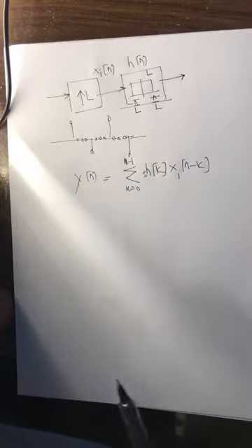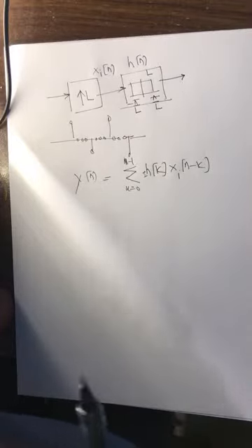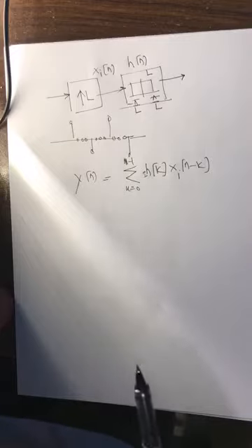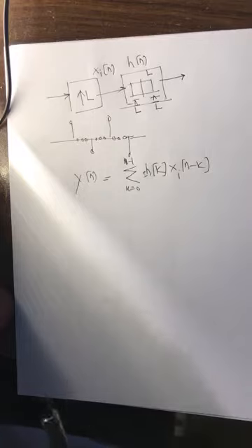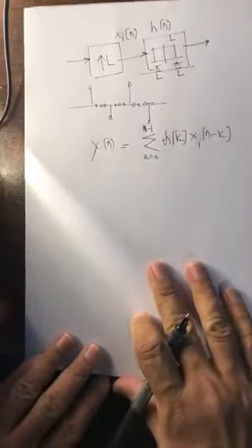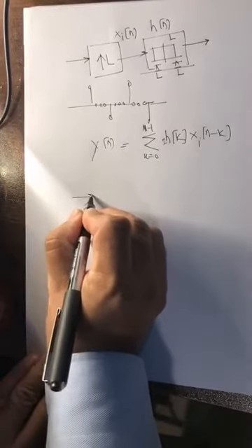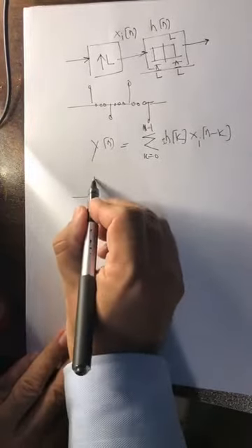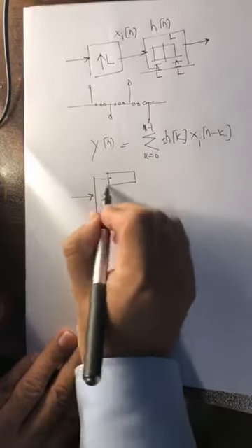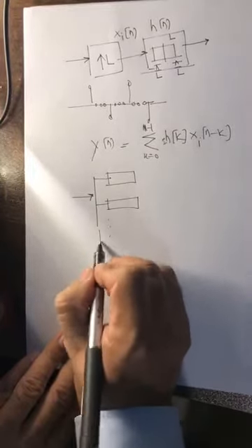For the same reason as we were using decimation filters, because we never wanted to compute something which we ultimately are going to throw away, we don't want to multiply numbers with zeros, because we know that this is just a useless exercise. So a polyphase decomposition also helps in interpolation. And in this, we do the same thing. You have a filter, you split that filter into multiple filters, so L number of filters. How? By just splitting the coefficients.